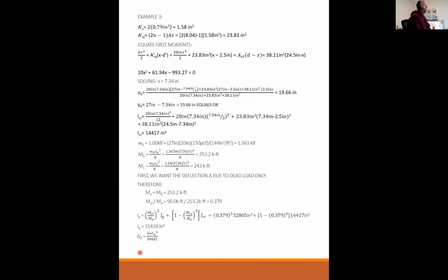So normally we design beams for kips per lineal foot because we really don't care what's framing into it. We already designed that. Now we're just trying to design the beam. So we use kips per lineal foot. Likewise, when beams are being supported by columns, by the time you get to the column, you're designing for kips. The reaction of the beam becomes the load on the column. So it's a load path. You're going from a big area to a line to a point.